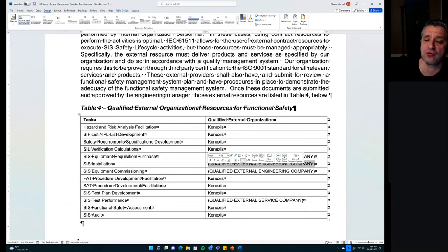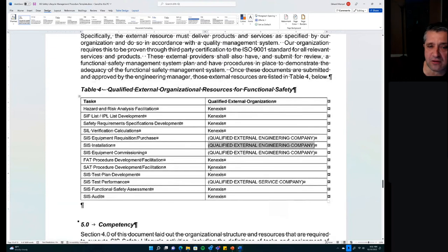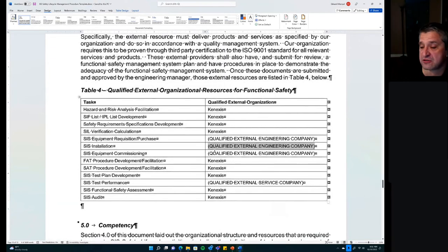So you need to go through a quality management process to review who your critical contractors are and verify that they have the systems in place to ensure compliance with the 61511 standard, especially related to planning and competency. Okay, so make a list of what organizations you're going to subcontract to, and you can even go ahead and put those organizations back up into table 1.